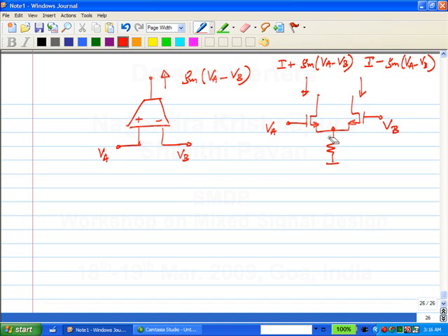So to make this depend on some phi 2, what I need to do is have a resistance which is there for some time and not there for some time. So you need a resistance which varies depending on control, and that is simply a MOS transistor operating like a switch. Correct?